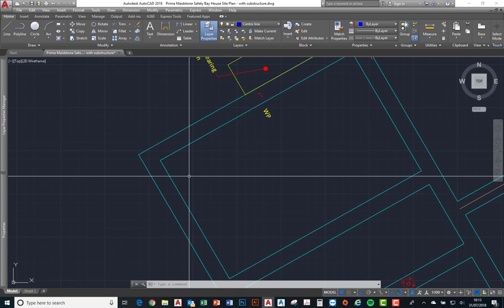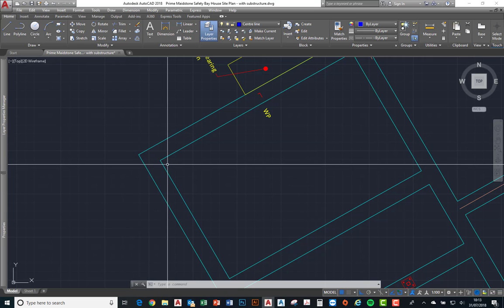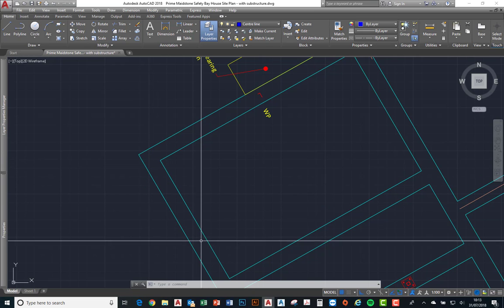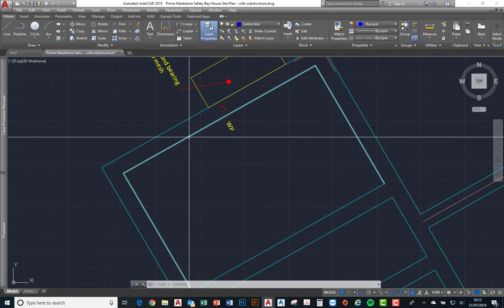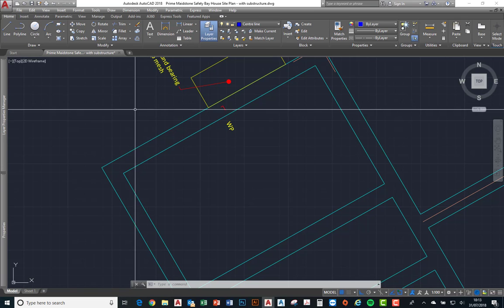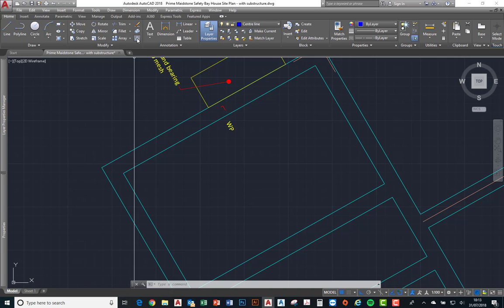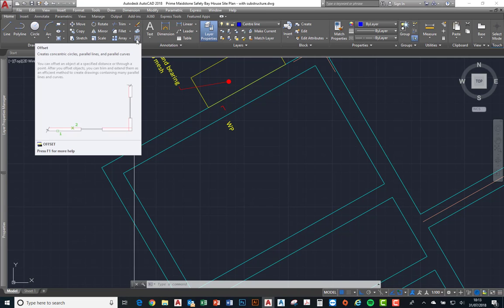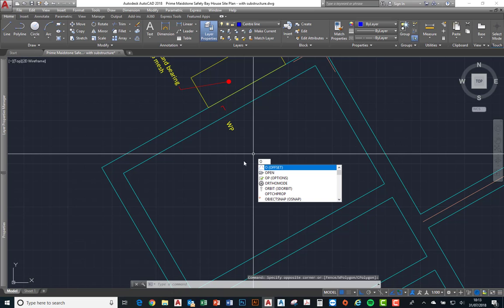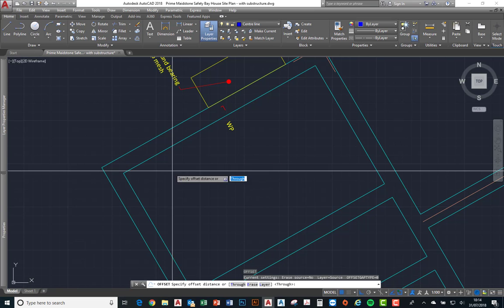So what we can do there is we can either draw a line from the end point to the perpendicular, and we can then take the midpoint of that line down. But the easiest way of creating a centre line for a dig is to use existing lines like these two and offset them. Now offset is available under the icon here which is offset, or you can do modify and offset, and you can also type in O on the keyboard, select that from there.